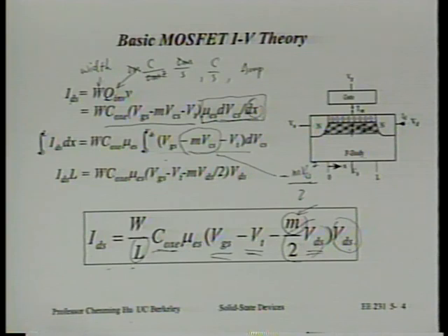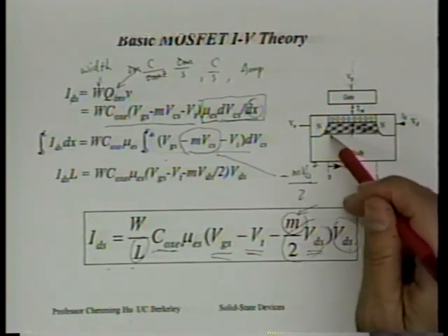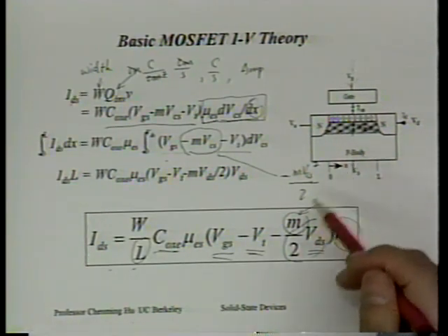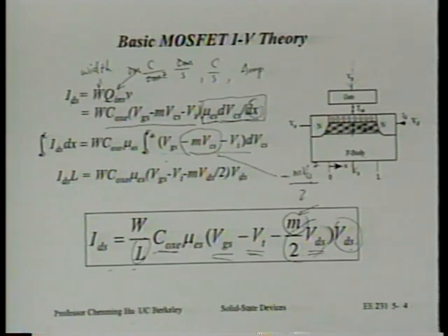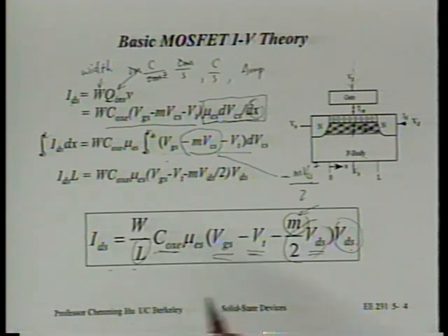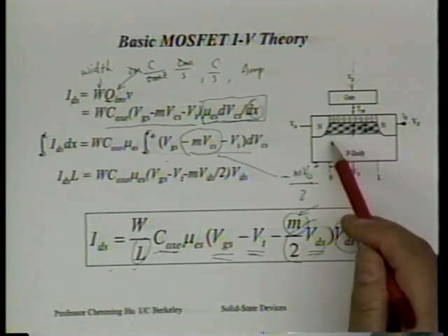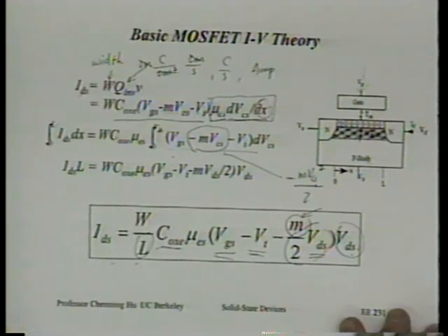Okay, why do I like this body charge effect? You can see now that this term kind of comes from the days of the uniform doping. The reason we're losing some of this current is because the gate voltage is not all used to induce charge at the inversion layer. Some of the gate voltage is occupied to induce some depletion layer charge. That charge in the depletion region, we call that the bulk charge effect. But now you know the depletion layer cannot increase, right? It's not like the depletion layer is expanding. It's as if we had a gate, almost as if there was a metal right underneath a fixed capacitor. In that case, do we really want to call that bulk charge, or is it better just to think of this as a back gate or a back capacitor? So bulk charge is not, I think, that descriptive a name for the phenomenon this is describing. Nonetheless, that's still the standard term. So the bulk charge effect, all right?